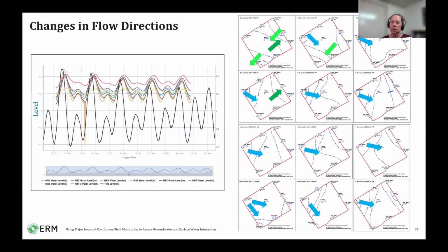So the overall message here is this detailed understanding of tidal cycle is really important because it helps to tell you when to collect samples to best capture the groundwater that is sourced from your site and is flowing towards the coast, so low tide or possibly soon after. And it also shows that manual gauging alone might not be enough to understand the main groundwater flow directions and pathways.